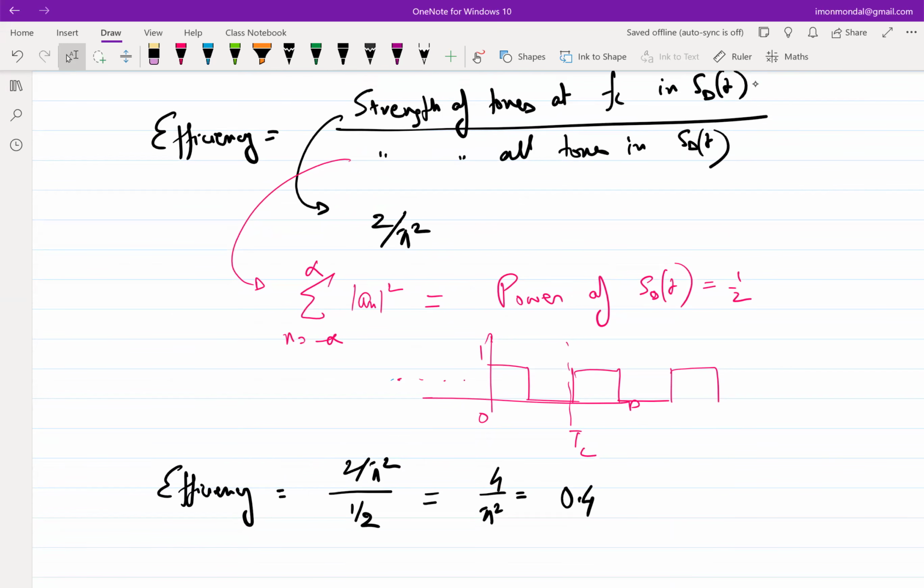Okay, mathematically, what you are planning to do to this waveform to cancel out the DC. The DC is how much? Half. So basically subtract half, right? That is fairly simple. You are subtracting a DC, right? That is fairly simple to do in circuits, right? You just put a capacitor, DC gone, right?